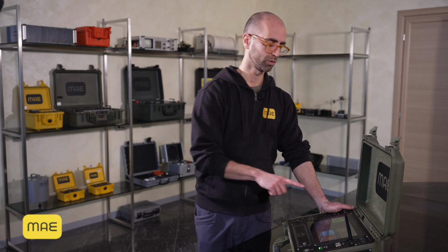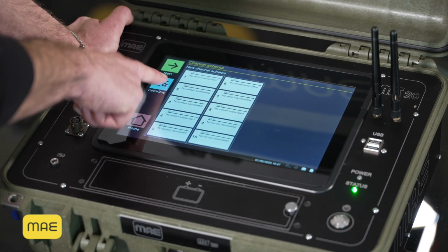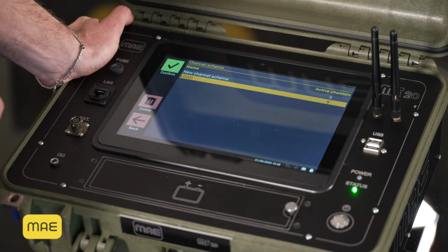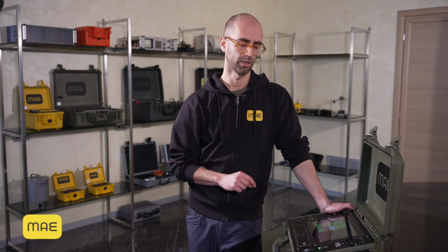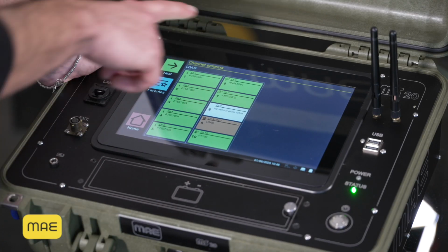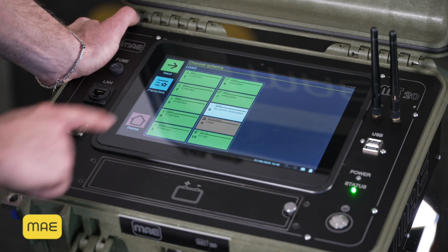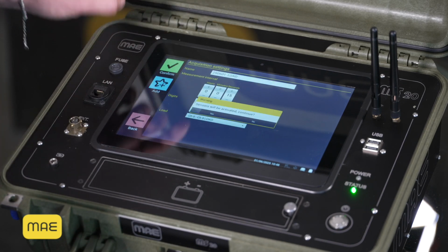As an example, we're going to recall one of the favorite measurement scheme. So we're going to favorite and select load that we previously saved. And here it's automatically coupled the sensor to the channels. We can see 5 transducer for displacement, 2 angle, 1 load cell, and 1 temperature as a probe. Next, we click on confirm.